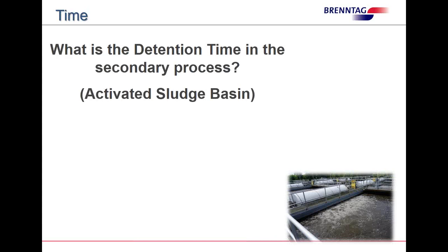Okay, so let's talk about time here. What's the detention time in that secondary process? How long does the waste stay in that activated sludge basin? We really need to know that because we want to make sure we keep it in there enough time, but it's not in there too long.